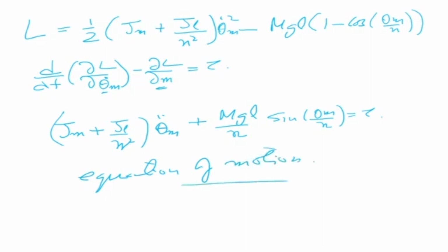So what we have done is found the equation of motion of a one link system using Lagrangian Euler dynamics. Now this is only one link. There you have inertia forces, which is this term, mass into acceleration. So this is my inertia term. Then this is my gravity term, so mgl is the gravity term. There is no centripetal or Coriolis force because there is only one link here. So no Coriolis and centrifugal.